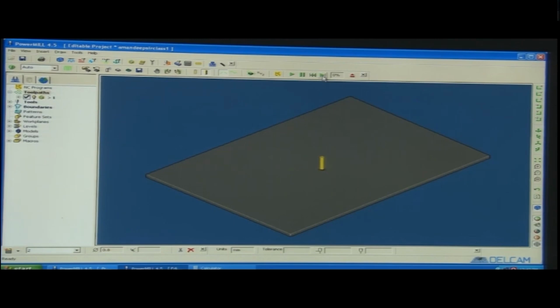So, it is going in 2 steps. It is coming back in rapid mode. See it again carefully. It is 5 mm above in rapid mode, now 3 mm down and 2 mm down in 2 steps. Now, in the rapid mode.